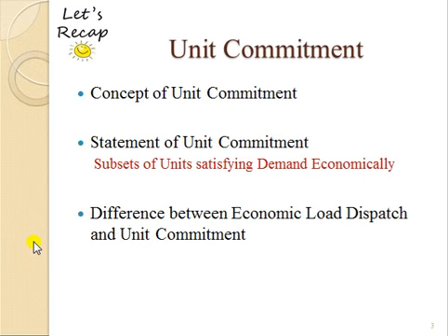Now then we can focus on what is the statement of unit commitment. The statement of unit commitment is, imagine there are n number of power stations, out of which you are making a small subset, and those subsets can satisfy your demand in the system, and that is also economical. And this brings the difference between your concept of economic load dispatch and unit commitment. Concept of economic load dispatch you have already gone through, and there we have seen for economic load dispatch you are applying some optimization to the unit operations which are already in operation. So here comes the difference, because unit commitment is nothing but bringing a unit into operation or taking a unit out of operation. Economic load dispatch is applied only to those units which are in operation.